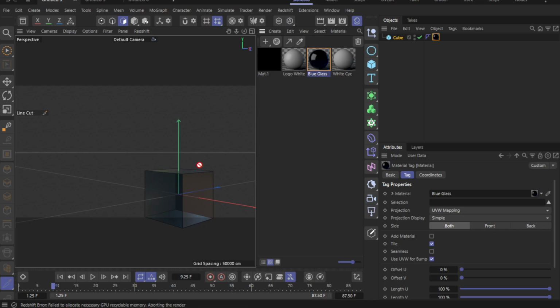For third-party renderers like Redshift or Octane, you may need to convert your video to an image sequence first. Then, in their respective material node systems, load the first frame of the sequence and adjust the animation settings, including the movie frame rate and the end frame, so the playback matches your project. This ensures the texture advances properly across frames and stays in sync throughout your shot.